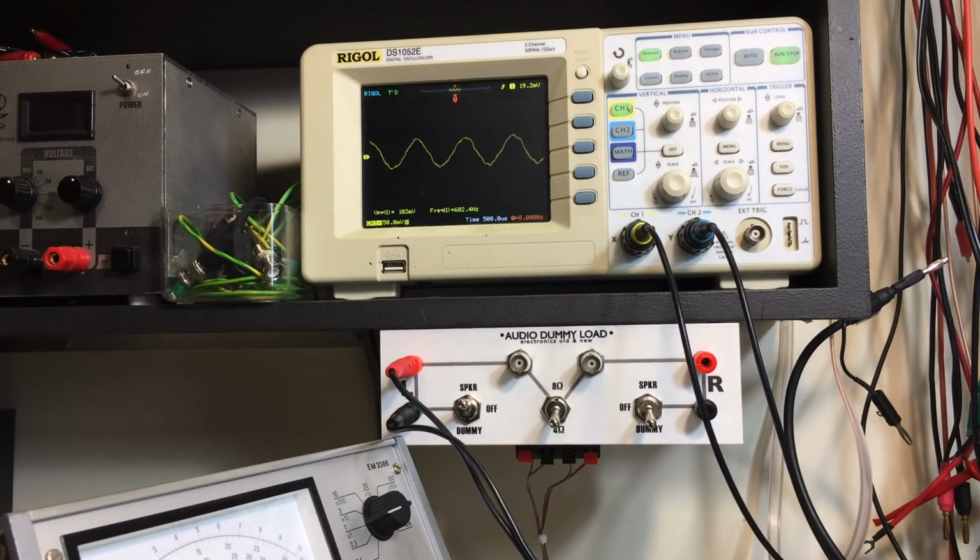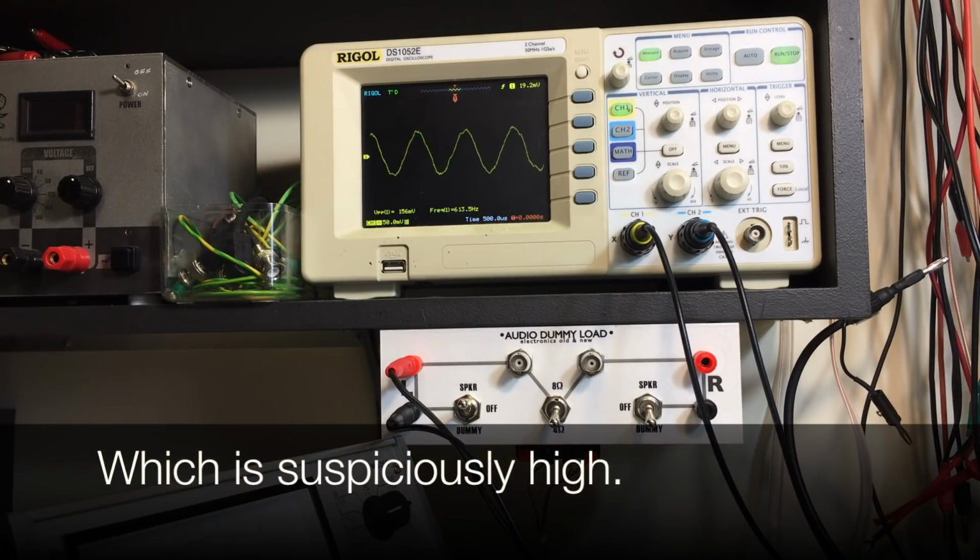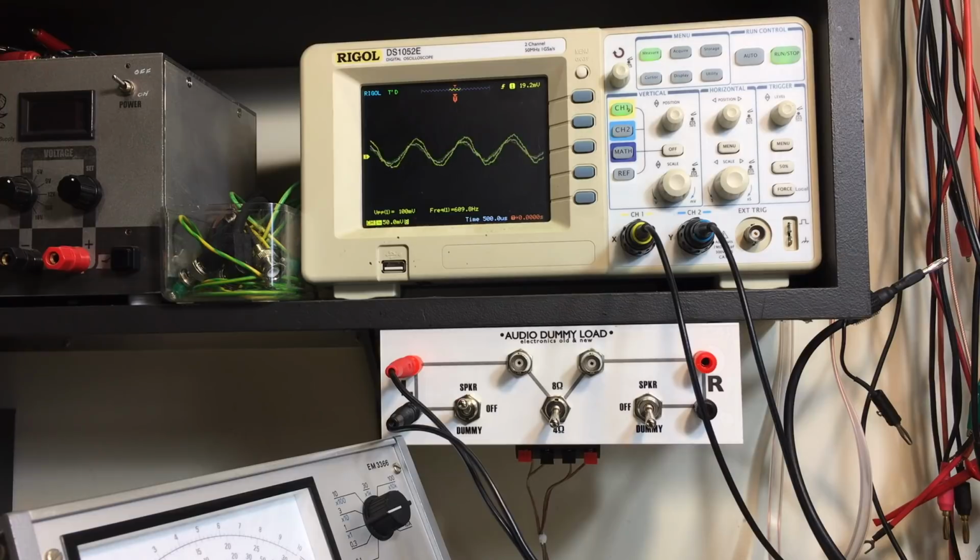Now, it's not a very strong signal. The 455 kilohertz carrier that I'm sending in is going in at 40 millivolts. And if I put it at 50, that's what happens. But I can see it at 40. I can actually see it at 30. I can still discern it as a sine wave. But 40 seems to be a good level, so I'll leave it on there. And now I'm going to connect up the voltmeter to the output.